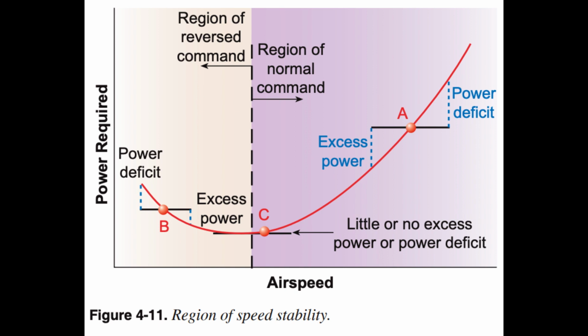For example, a pilot is on an instrument approach at 1.3 VSO, a speed near L/D max, and knows that a certain power setting maintains that speed. The airplane slows several knots below the desired speed because of a slight reduction in the power setting. The pilot increases the power slightly, and the airplane begins to accelerate, but at a slow rate. Because the airplane is still in the flat part of the drag curve, this slight increase in power will not cause a rapid return to the desired speed. The pilot may need to increase the power higher than normally needed to maintain the new speed, allow the airplane to accelerate, then reduce the power to the setting that maintains the desired speed.